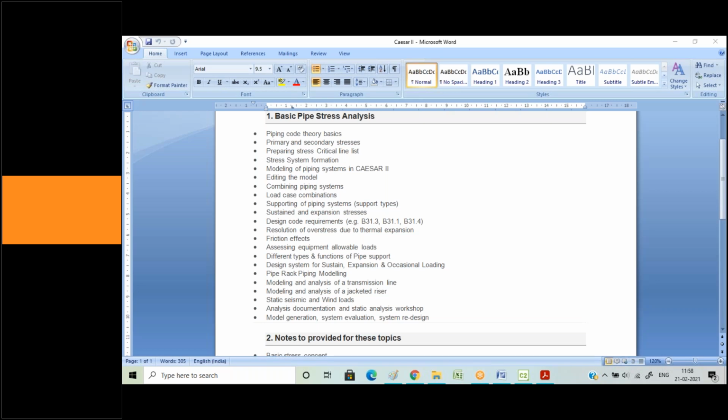Whereas a spring is that certain little innocent child whom you say, okay, you're supposed to do this, you're supposed to do that, you're supposed to move like this. It will actually follow the orders of the line, and it will align itself according to the movement of the line without increasing the stress in the line and acting like a support in the line. So that is why we place a spring rather than placing a rigid support.